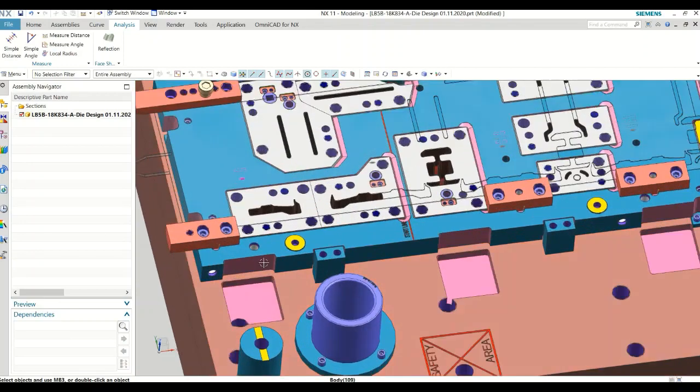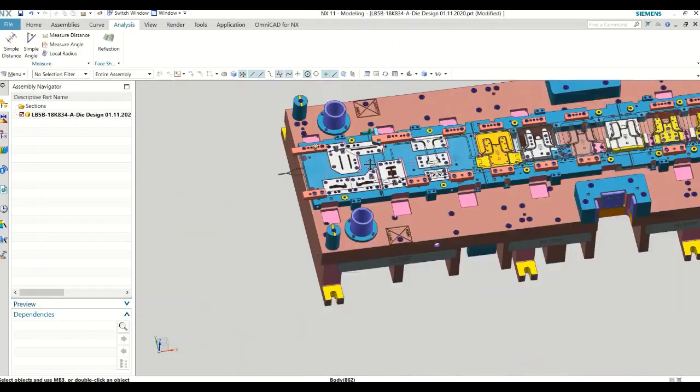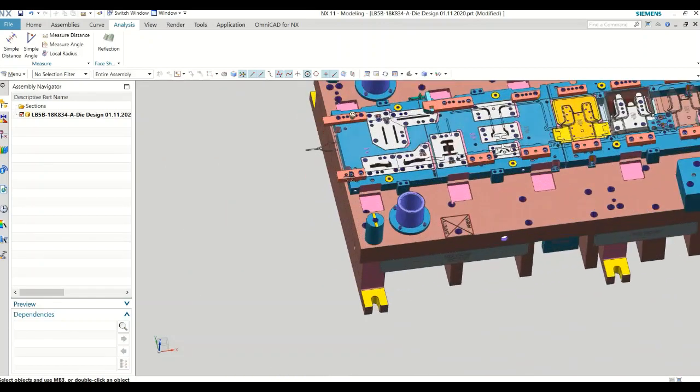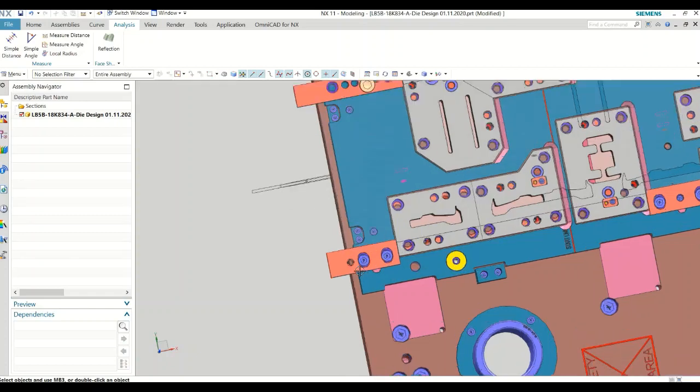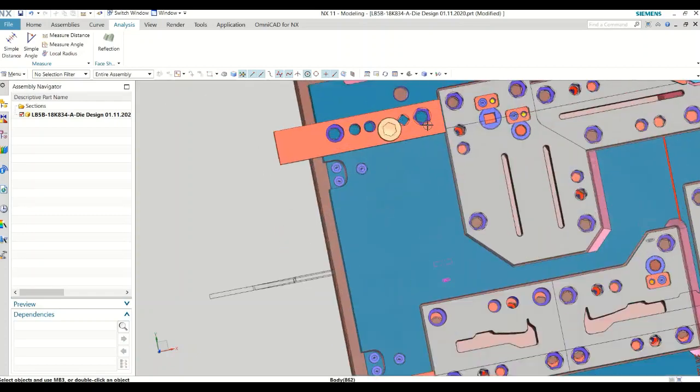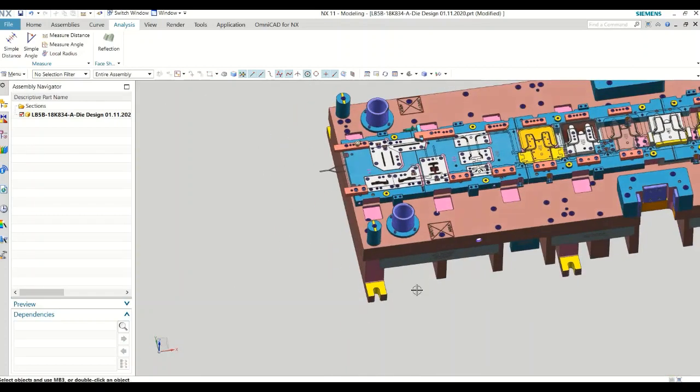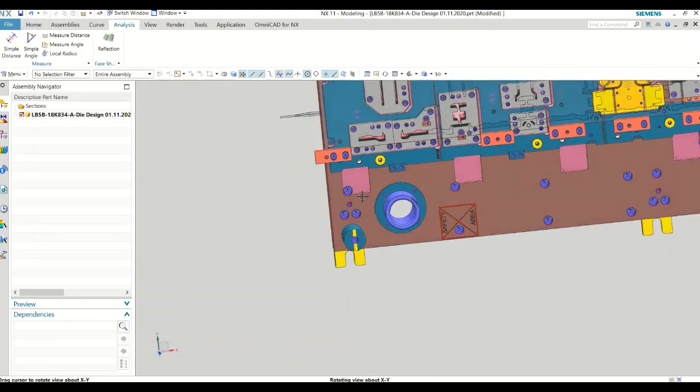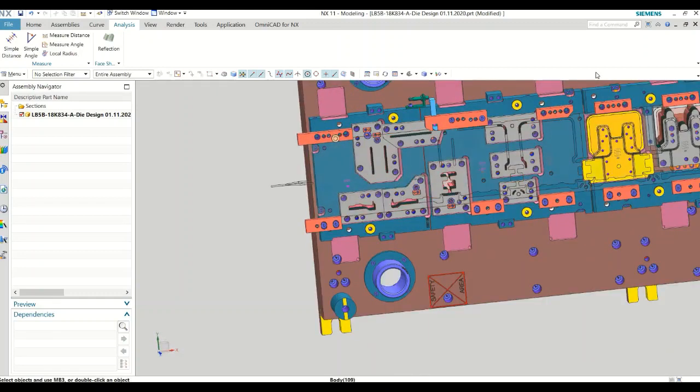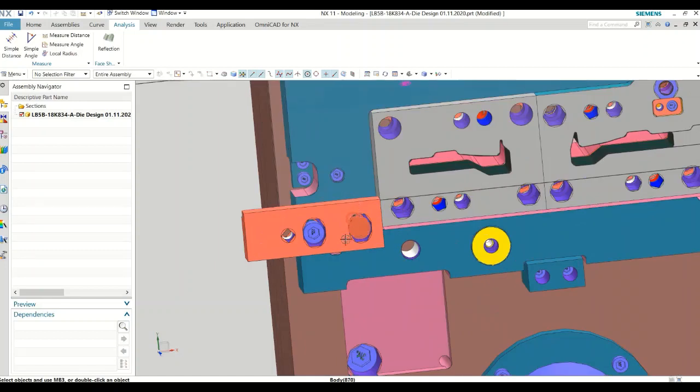Now these are stock guides. Here is a stock guide, here is a stock guide. You see these two are movable and this one is fixed. This is the front side. Because our stock, that coil width, could be less or more. It has a tolerance. So within that range it might be less or more, so you need to adjust it. During setup, you might need to move it in or move it back.